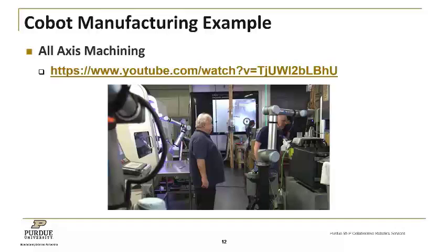And then they had an operator who made his own job easier by programming the robot to do a sanding operation that he himself was doing. So it made his job easier, just picking up the teach pendant, the tablet, and programming the robot himself to do the task. And then they were able to put the robot on wheels. I don't know if you're able to see that. They have some casters on a mobile platform that they could lock into place, and they would just unlock the casters, roll it around to another station on the factory floor, and then lock it into place and have it going on the next task.